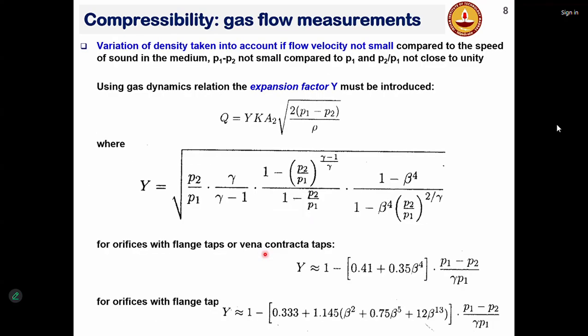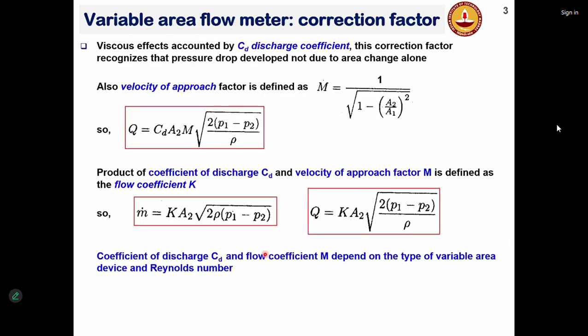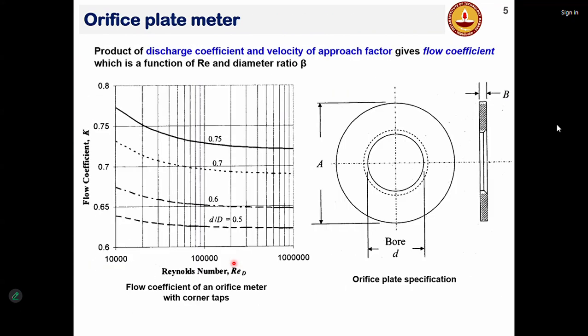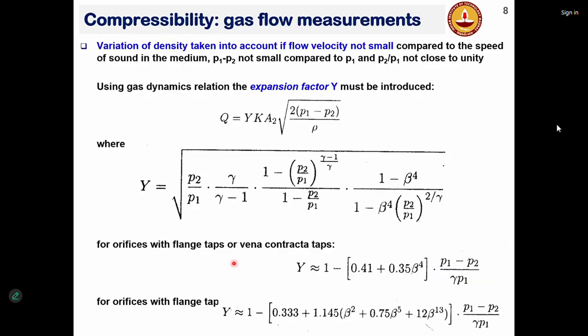Now, when you have incompressible flow, then all these formulas that you have work fine. When you have compressible flow, that means you have fluid like air, and over a Mach number of typically 0.3 is considered to be compressible flow.